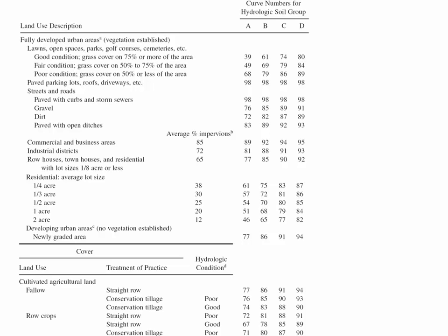Oh, I've got bad news. You've got class D soil on your property, is what a hydrologist might say to a landowner. And the landowner would say, I guess that means I have to put in a big culvert. Because if that landowner had had good quality soil, an A or B soil, then there'd be more infiltration, and so the structures required to accommodate the stormwater runoff would be less substantial.